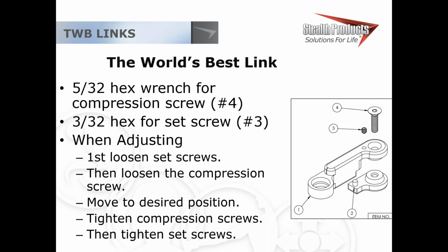If you're loosening or adjusting, you always want to start with a set screw. Loosen it and make sure it's completely free and clear of everything before you start to mess with that compression screw. So that cleat is actually putting a longitudinal pressure on your threads, right? So it's pushing things in opposite directions and putting things off-centered, so you're binding up your compression screw. If you release that pressure, compression screw releases easier. Now you can tighten it.